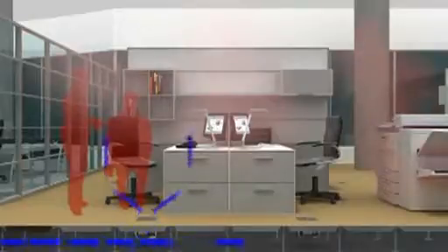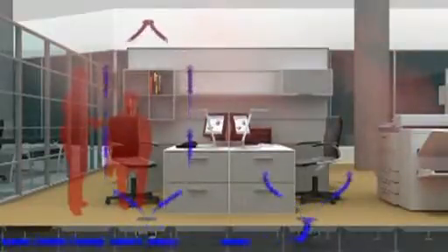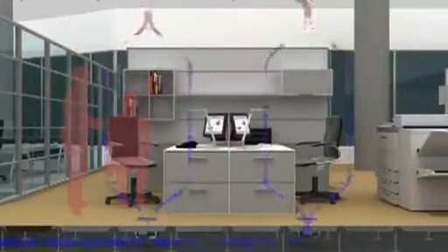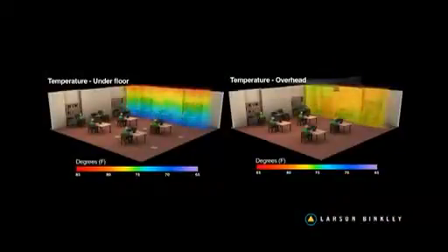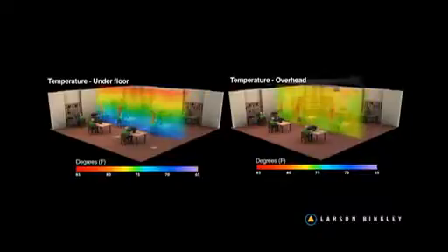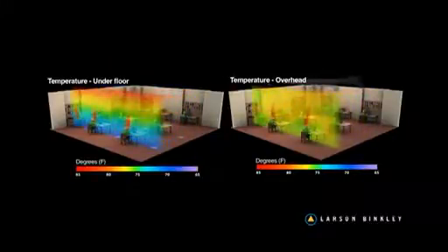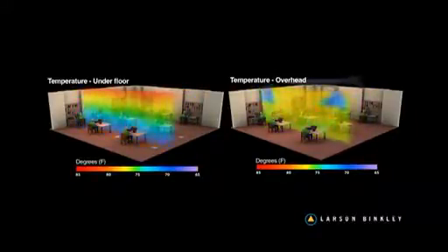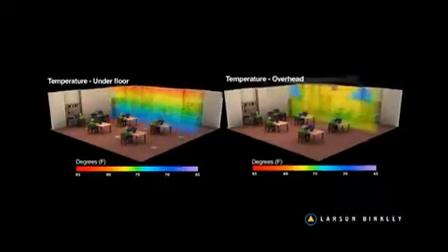If you think about the way heat rises off the pavement, or heat waves, that's an easy mental depiction of what happens with heat sources in a room. Heat will rise from the source, and if left undisturbed, it will rise out of the occupied space, stratifying near the ceiling. These graphics illustrate a typical temperature profile of an underfloor air distribution system and a ducted overhead system. The redder the color, the hotter the temperature.